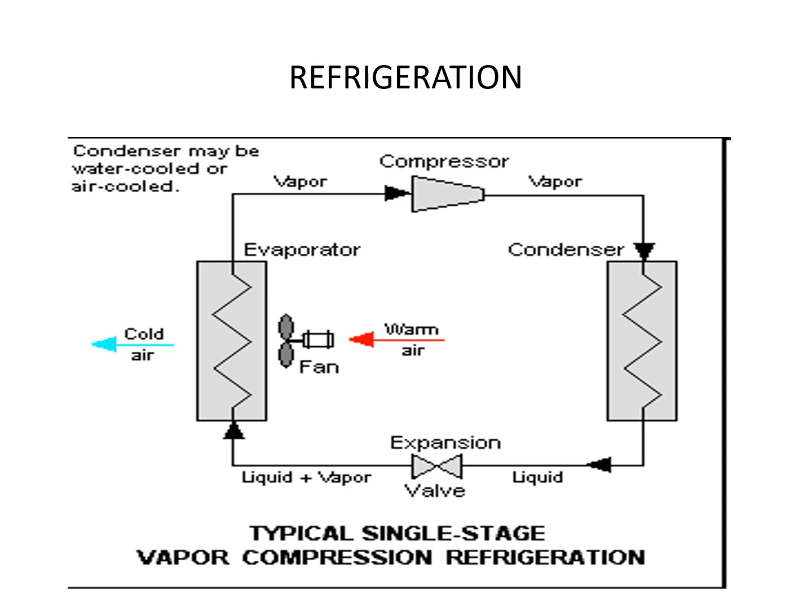In the compressor, the vapor will be compressed to high pressure. Then the vapor will pass over to the condenser. In the condenser, the phase change occurs. The vapor gets phase changed to liquid. Then the liquid enters the expansion valve. In the expansion valve, the pressure will be released. Whatever pressure is maintained inside the refrigerator will be reduced. Then it will be partially expanded. So the liquid plus vapor enters the refrigerator again and the cycle continues.